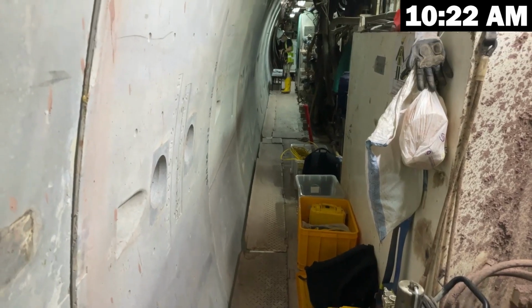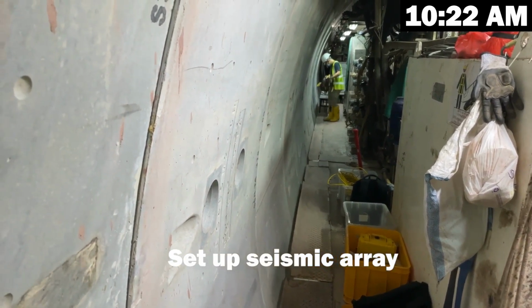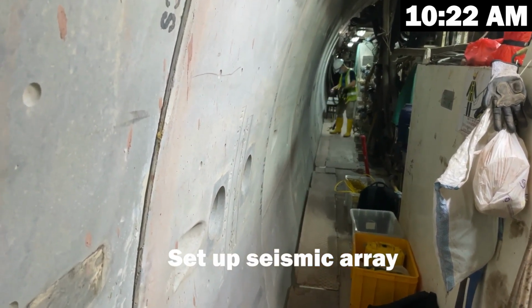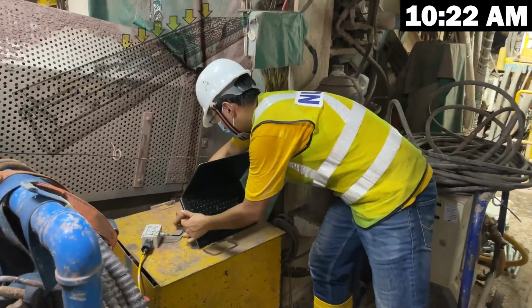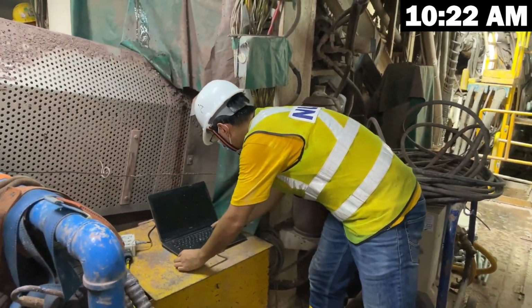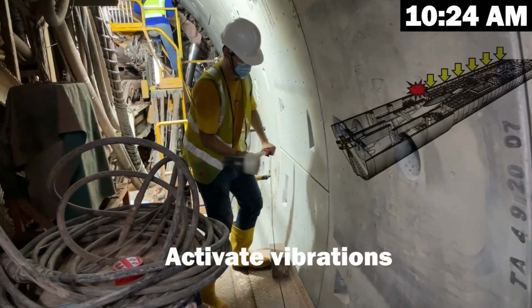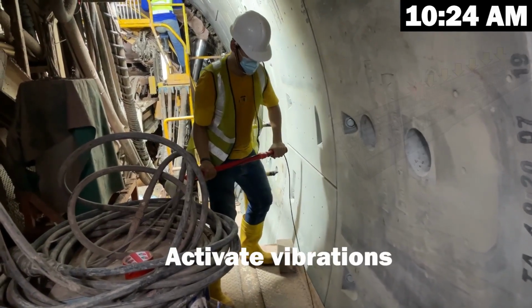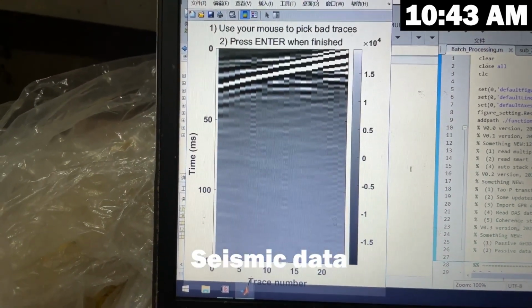The method of using a hammer for activating seismic waves is called the active method. Firstly, we deploy our geophones on one side of the tunnel and connect all the lines to the computer. And then we use the sledgehammer to activate the seismic waves. Here we can see the one-sided seismic profiles for quality control. For one-sided data observation and imaging, we only need less than 25 minutes.